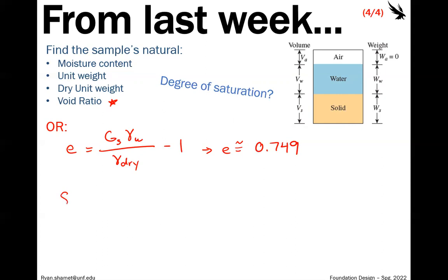All right, so we know the degree of saturation is also the volume of water divided by the volume of voids. But then there's another equation that is super useful for this. That's kind of a shortcut. Does anyone remember that saying, or the thing we talked about last week? Yeah, Soil Engineer equals George Washington, or whatever you want to use to remember it. Again, I don't know why it stuck in my head as sewage, just seeing it as SE equals WG. You just spell out sewage and that works somehow. But we could also do this math since we have everything.